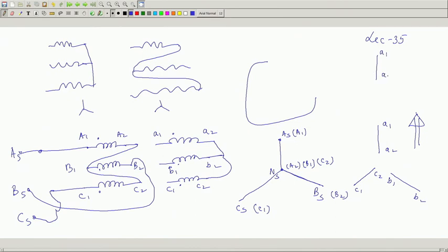So, A1, A2 and this B2 is there, but B1, B2 will be parallel to this fellow, you cannot do anything. So, move it parallel, bring it here. Here is the most important point, B2, B1. C1, C2, C2 has been joined with A2, B2, therefore, it will be like this, C1, C2, that is what you will get. Length of each of them will be 100 volt, provided you have applied here 200 root 3. Length of this is 200. So, 100 volt, 100 volt, 100 volt, and then he tells that okay, from this you take the 3-phase output.